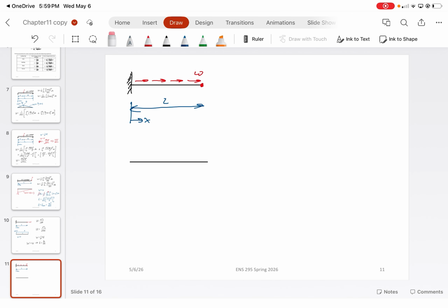Anyone? Yeah. Is it a slope upwards? Yeah. Well, so basically we would get a reaction force here, which would just equal W times L, right? And so we would have, that should be blue, WL at the top, and then it slopes down to 0. So then N of x is just equal to W times (L minus x).